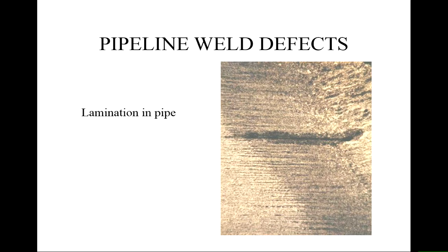But what happened during welding? During welding, because of the stresses that are born during solidification, again, stresses that are coming from where? From the mismatch in the contraction during solidification between different phases. So by imposing residual stresses on this lamination, it will lead in time to what? Well, add a prefix to this one, delamination. It will tend to open.